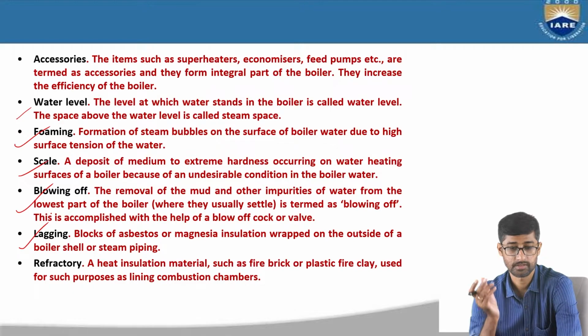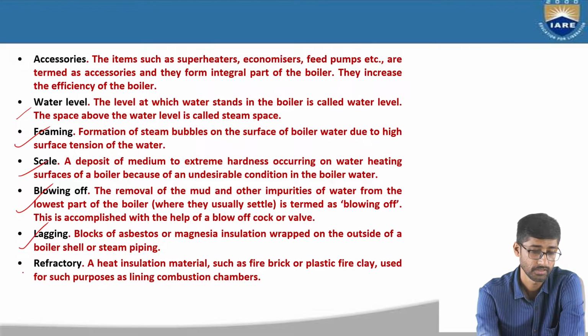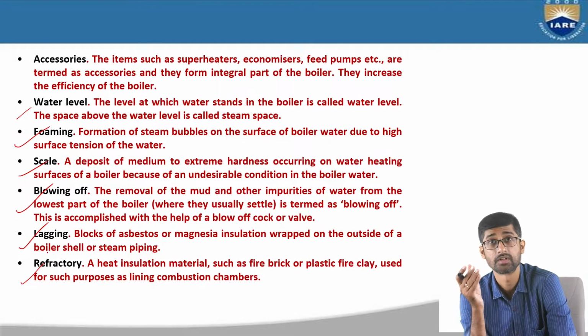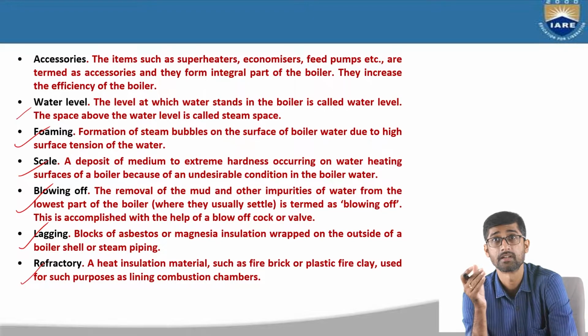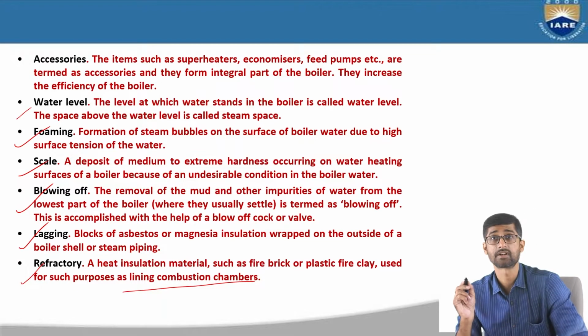Blocks of asbestos or magnesia insulation wrapped on the outside of a boiler shell are called lagging. Then refractory, this is very important for heating. The insulation material, such as fire bricks or plastic fire clay, is used for such purposes. The lining of the combustion chambers is called refractory.